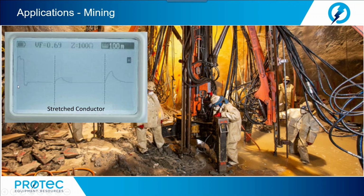Now, here in the screen capture, we show the representation of a stretched cable conductor. It increases the longitudinal resistance of the metallic wiring, causing an increase in impedance or a positive reflection. Now here we still have continuity. We have added resistance due to the stretching of the conductor, and we are still able to see the end termination or the end of the cable.